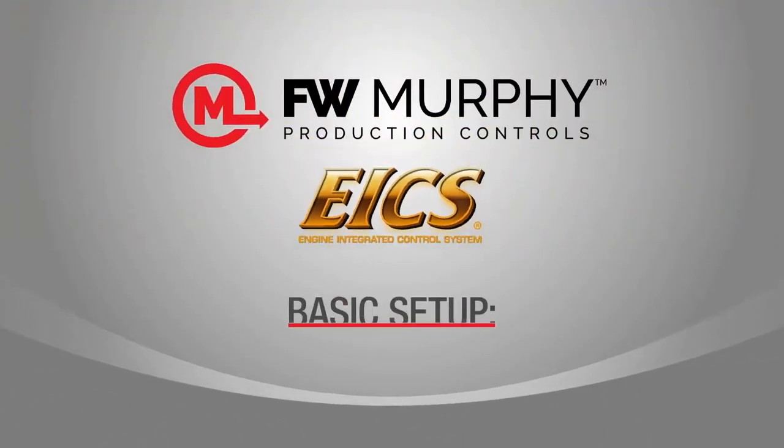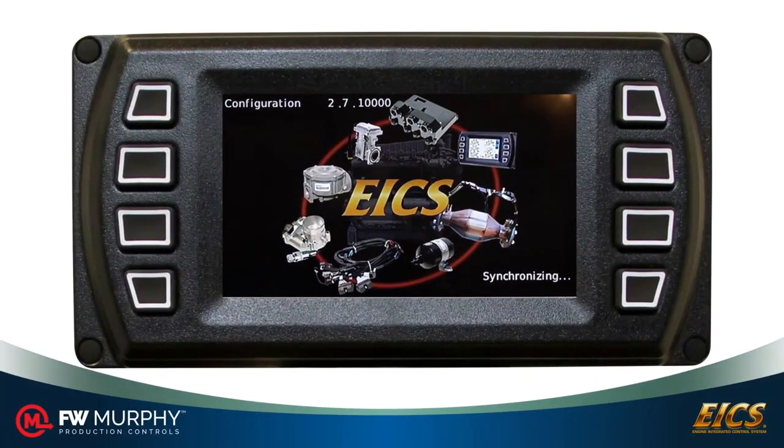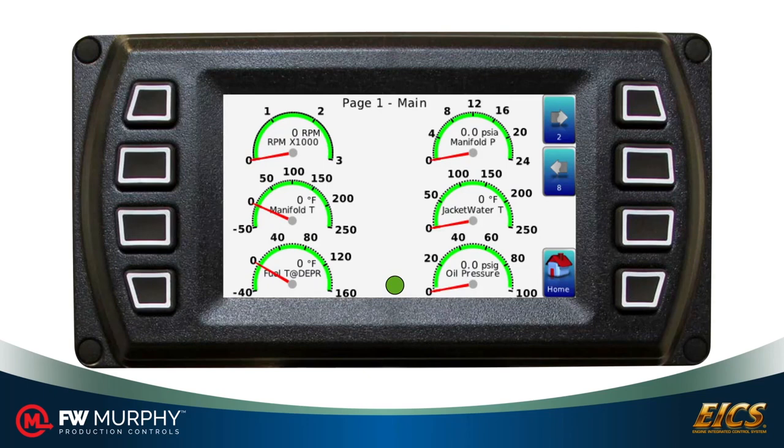Basic Setup, Navigation. On power up of the ECM, you'll see the logo screen pop up. The ECM and the display synchronize. Once synchronized, the main screen opens. From this screen, you can see all the operating parameters of the engine: RPM, manifold pressure, manifold temperature, jacket water temperature, fuel gas temperature into the DEPR, and the engine oil pressure.